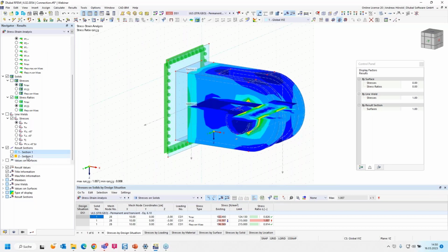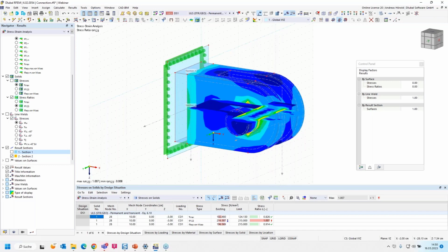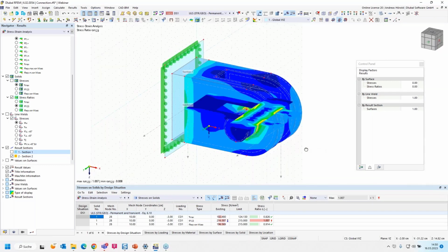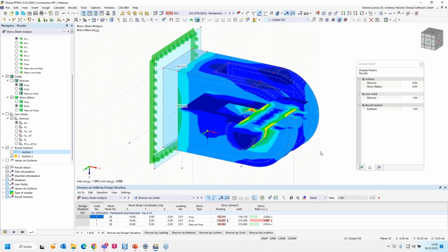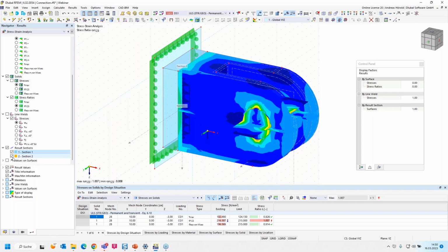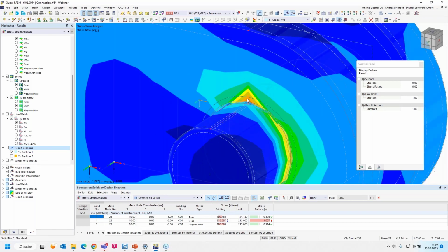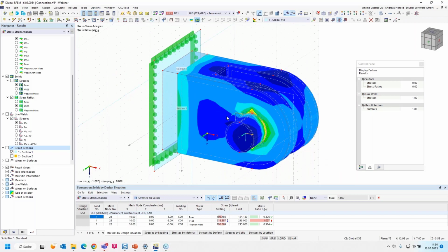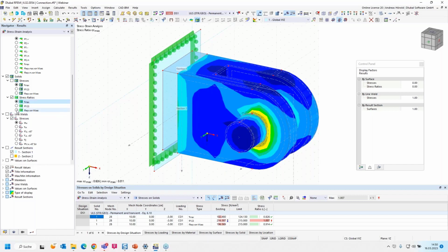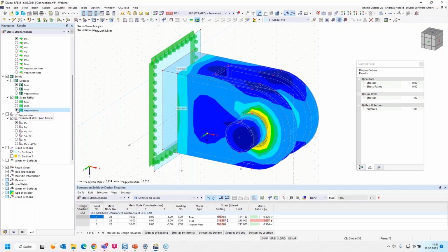Yeah, that's all. And if I only activate section number 2, I can take a look at the results. Yeah, and then you can print such sections in the printout report. And in that case, here seems to be the maximum value. I print only this view here in the printout report, but for example, for the principal stress, tau stress, and the equivalent stress. How to do that? Here left at the top, print graphics to printout report.